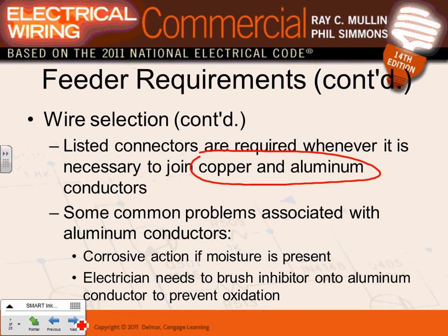Typically, if you have switchgear, the lugs will be rated for copper or aluminum. Bring it on, torque them, done. If you want to put one cable copper and one cable aluminum, why would you do that? Phase A, all copper. Phase B, all aluminum. They're sitting at different lugs anyway, so it doesn't matter. Can I do that? Yes. Does that make sense? Phase A copper, phase B aluminum, and phase C copper again. You can do that as long as the lugs are rated for copper or aluminum.